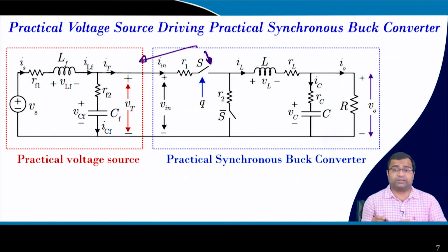impact the supply voltage. If the supply is very well regulated, with very high bandwidth or maybe a very large capacitor, then it will try to hold it, right. Otherwise, most of the power supplies we are getting presently are basically SMPS type. Earlier, power supplies were quite bulky, based on the linear transformer, that means a 50 hertz transformer. But now most power supplies come with a high frequency transformer and a switch mode power converter, because we need to reduce the size of the supply and make it lightweight.